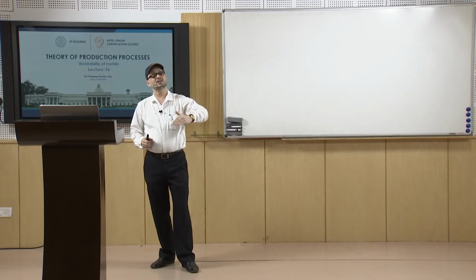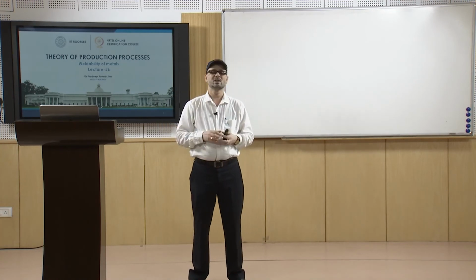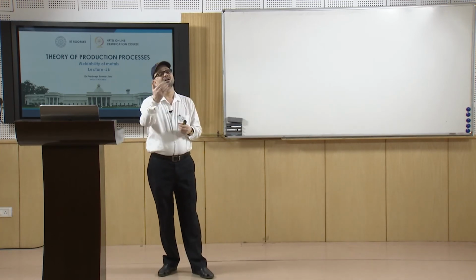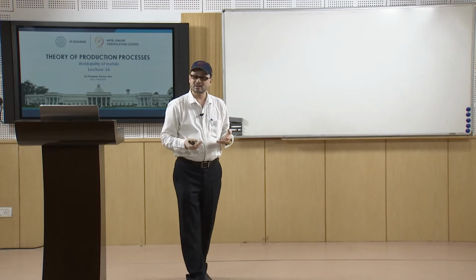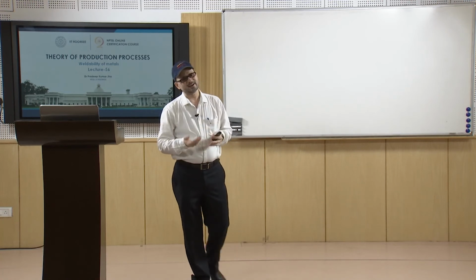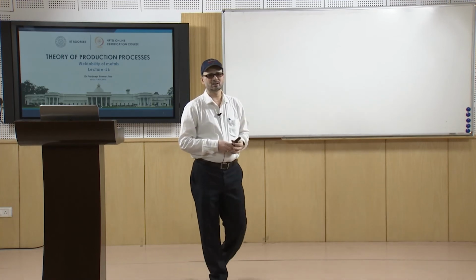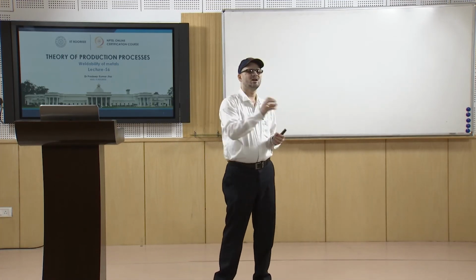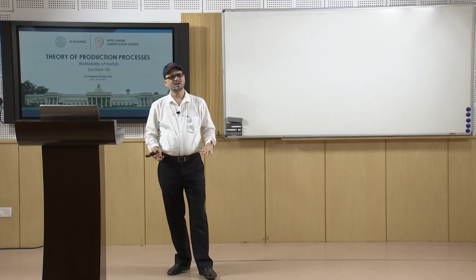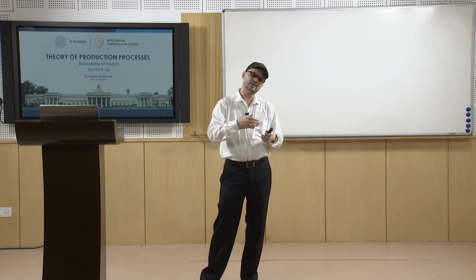Similarly, when you are doing the welding of certain composite materials, you have the parent material which is softer and lighter, and then you have the reinforcement. They have different properties altogether. It may be lighter, it may be heavier. If it is heavier, when you are doing fusion welding, it may settle down at the bottom. So, you will have segregation of the alloying elements, and that will not give you the same property as that of the parent material, and then you will say that weldability is poor.